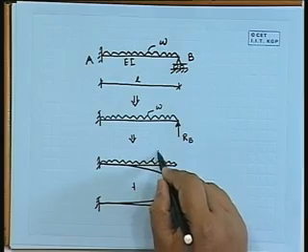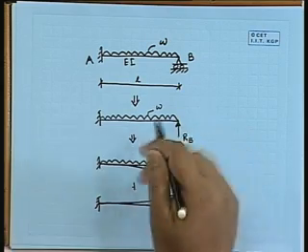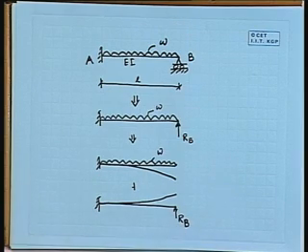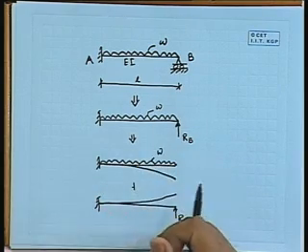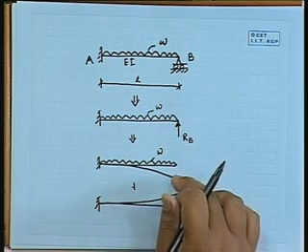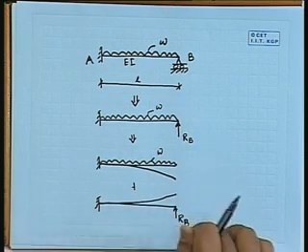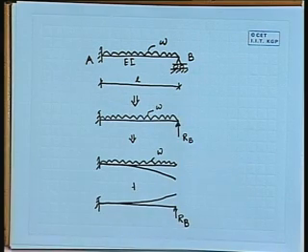Now, here there are two loads, one is omega. So, in the first step we have put this distributed load, and this RB we have removed, which we are putting in the second step. So, that force and this force are applied separately. So, the deformation of the beam subjected to W and the deformation of the beam subjected to RB, if we combine, we are supposed to get the deformation of the actual structure.